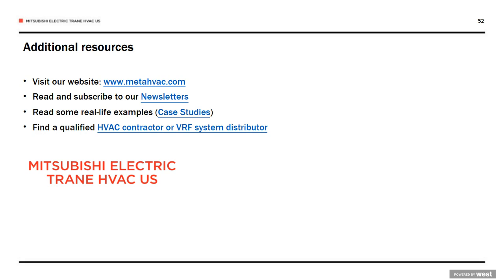Great. Next question here. If your building needs a DOAS that requires ductwork, does that offset the benefit of a VRF system not needing ductwork? I wouldn't say it offsets it. You know, the DOAS and ventilation in general, as an aside, are becoming a much more common part of HVAC system design around the country and around the world. We're seeing an increased demand for flexibility in ventilation solutions to be applied. The good thing about DOAS is that it can work two ways. You can couple it with a HVAC or VRF system, or you can completely decouple it.